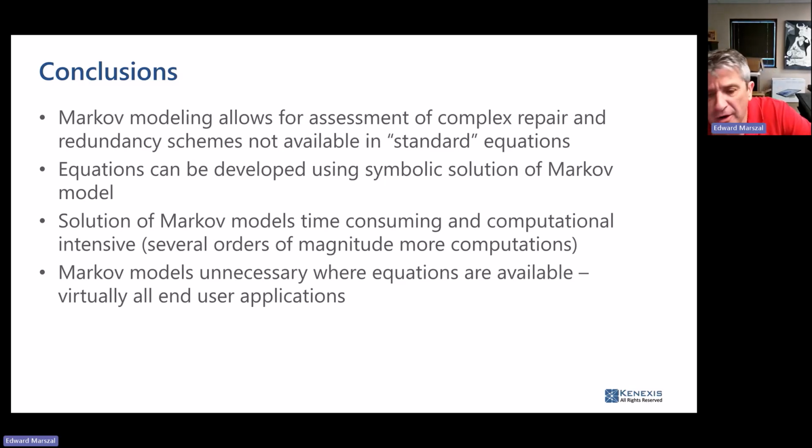Beta factor, I didn't show a Markov model that had a common cause failure state, but you can model a common cause failure state in any fault propagation model: fault trees, reliability block diagrams. There's nothing unique about how a Markov model handles beta factors that can't be handled in any other model.